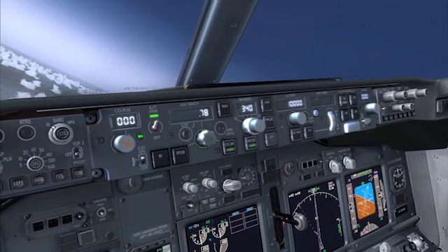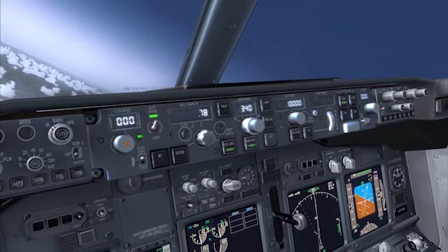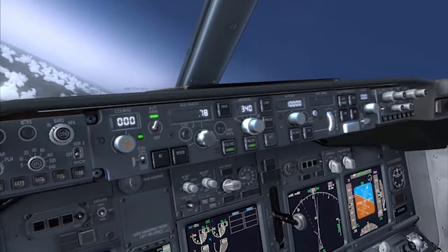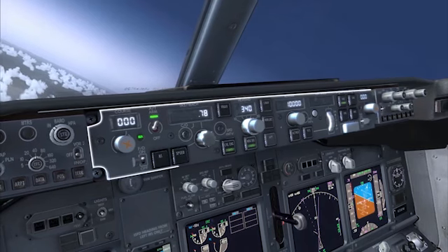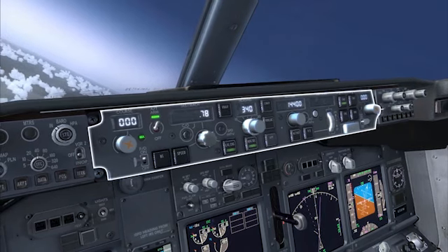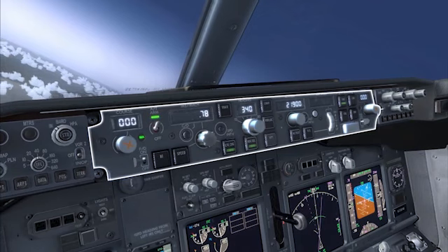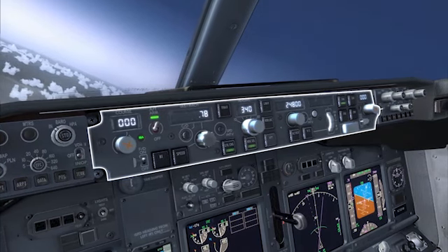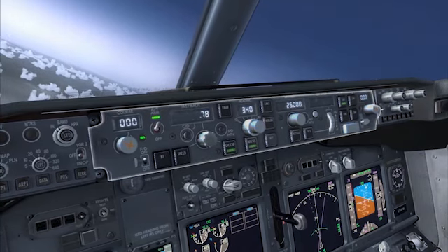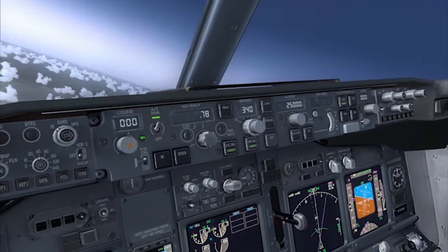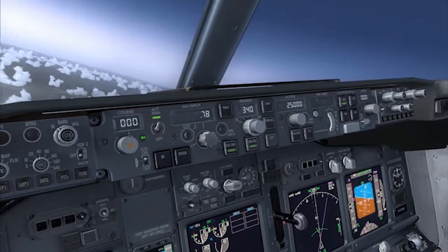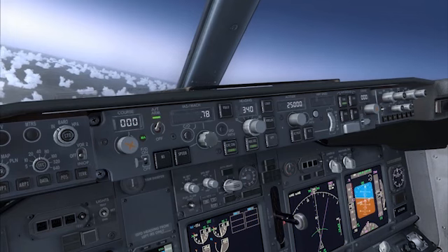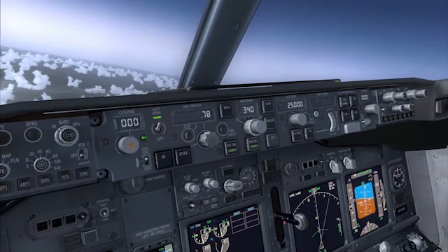The main means of interacting with the AFDS and FCCs is through the Mode Control Panel, which we'll call the MCP. This is a panel that you'll learn to be intimately familiar with as you progress through flight work and line work. One philosophy of Boeing that differs from other aircraft manufacturers is the ability for total pilot control at any time.